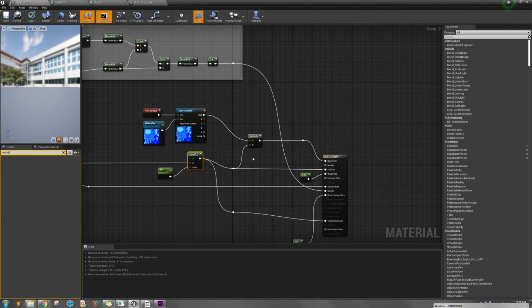Probably you can set up some threshold here, not 100% affecting the albedo, because you may want the direct light to make it brighter, so you can tweak how much percentage you want to affect the albedo and also the specular. In my case it is 100% when I turn the AO to 100%.